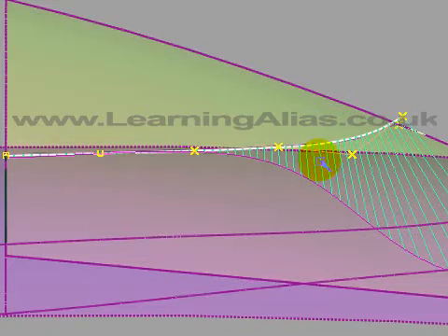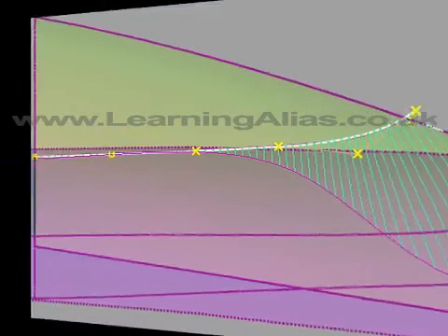Let's try to do that. And then put a comb on it, and the most important thing is that there are no inflections here. It wants to be fairly straightish along here, and then have a nice curvature up there. We're not going to deal with the whole shape of this in one projection. We're going to use 2 projections to do it. So this is our first projection. Having done that, you can project that onto this large C-pillar primary surface.